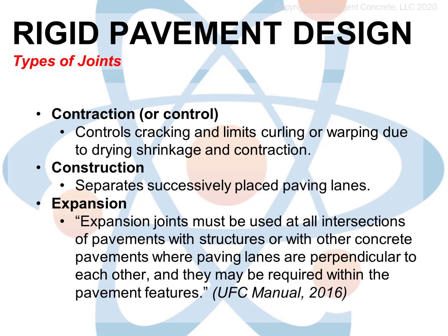Our pavement will be designed with transverse joints at 10 feet spacing with slip dowels to hold these slabs together. We'll talk about this a little more in just a second.